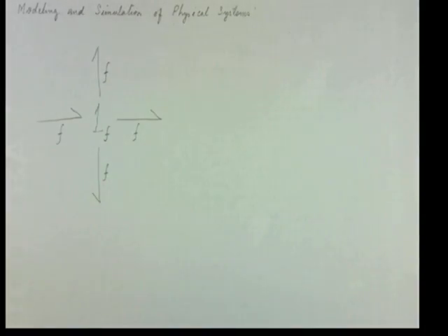Now suppose in this one junction, if a flow is to be maintained, or if it is to be respected, that suppose two bonds bring in the information of flow. If two bonds bring in the information of flow, what would happen to the one junction? Would it be able to maintain its relationship? It's possible that the two flows that are brought into the one junction may be different. In that case, the one junction would be in a dilemma, which flow to accept.